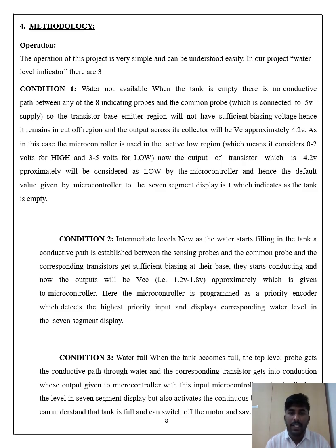Condition 2, intermediate level. Now as the water starts filling in the tank, a conductive path is established between the sensing probes and the common probe, and the corresponding transistor gets biasing at the base.